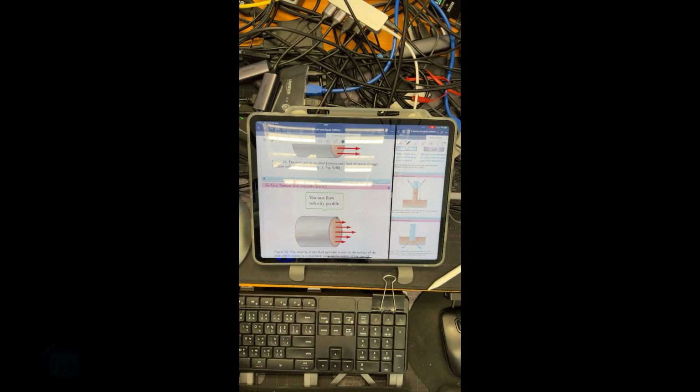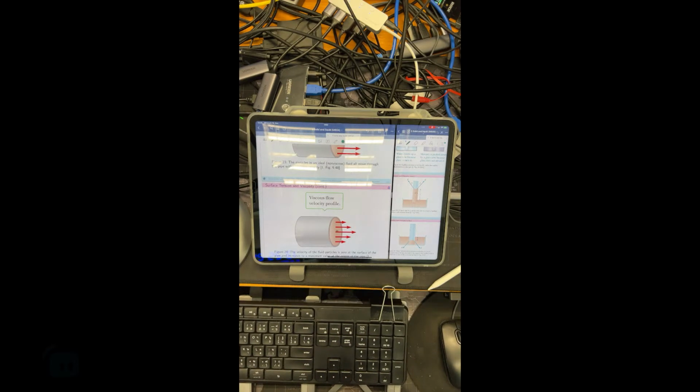There will be friction between the fluid and that solid, and that will cause the obstruction, and the fluid close to the surface inside the pipe is going to have lower velocity. Here in the middle of the liquid, it has only the friction between nearby layers of that fluid, so the friction is not high.